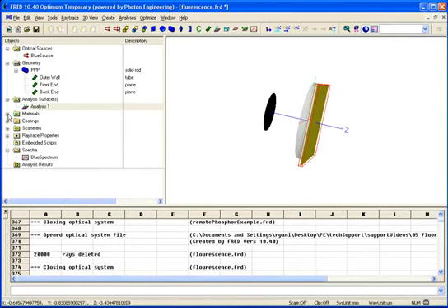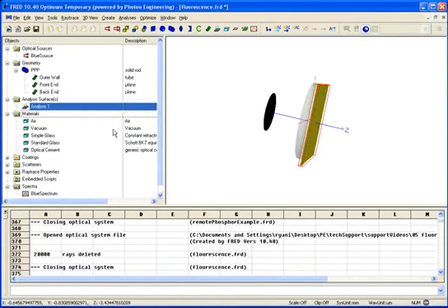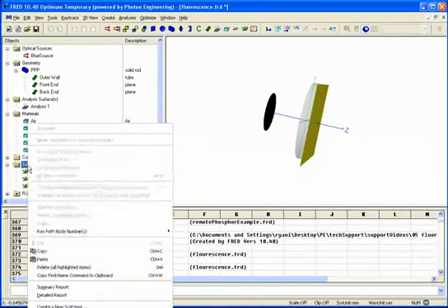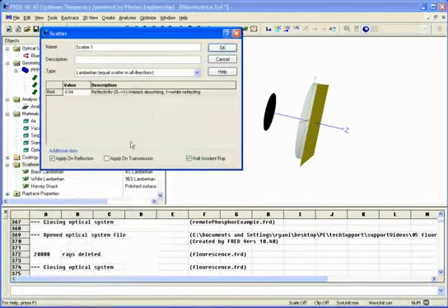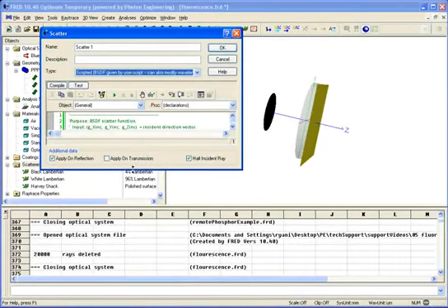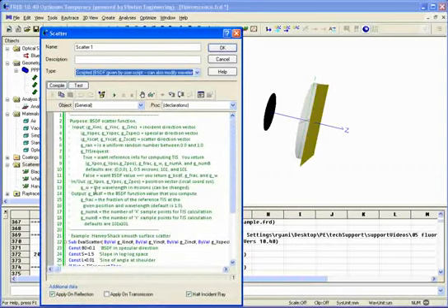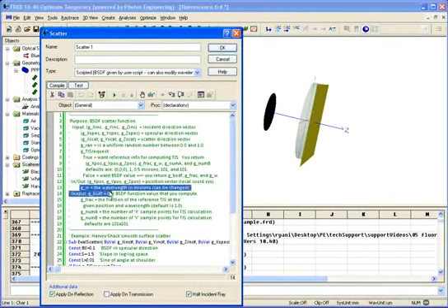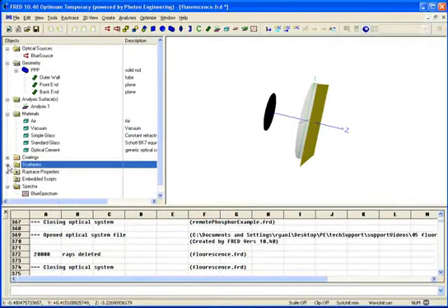Now how are we going to model the wavelength changing phenomena? There's two places that we have access to change the wavelength during a ray trace. That's going to be the scripted surface scatter model. So I could have created a surface scatter model, go create new scatterer. We'll do scripted BSDF. Let me expand this out so you can see it. And you can see that one of the parameters we have access to here is G_W, which is the wavelength of the ray. I'm going to go ahead and use actually a volume scatter model.